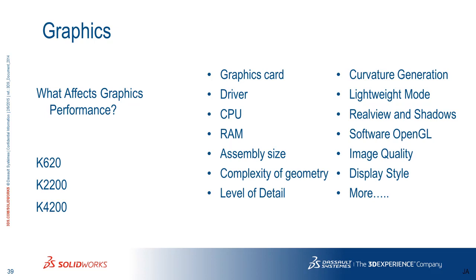Yeah. So as far as graphics go, we teamed up with NVIDIA this year. Again, they gave us a K620, K2200, and K4200. And what we're looking at is what affects graphics performance. When we look at this list here, these are all the different things that can affect our graphics performance. Everything from the graphics card, driver, CPU, image quality, display style, lightweight mode. All of these different things have an effect on graphics performance. And we'll look at some of the most critical ones that we see for day-to-day use of SOLIDWORKS.